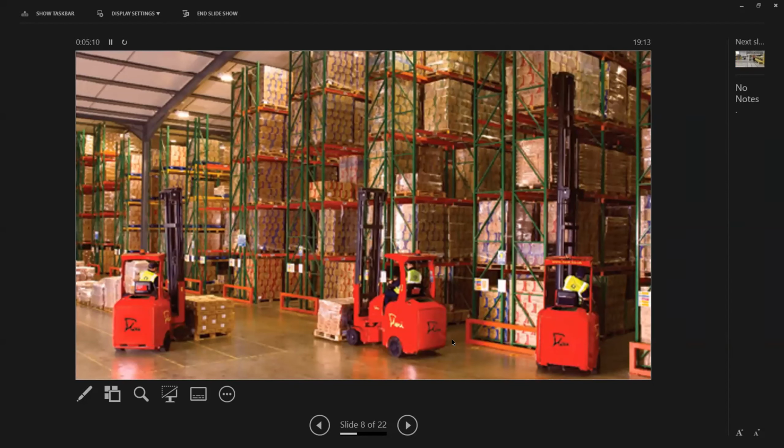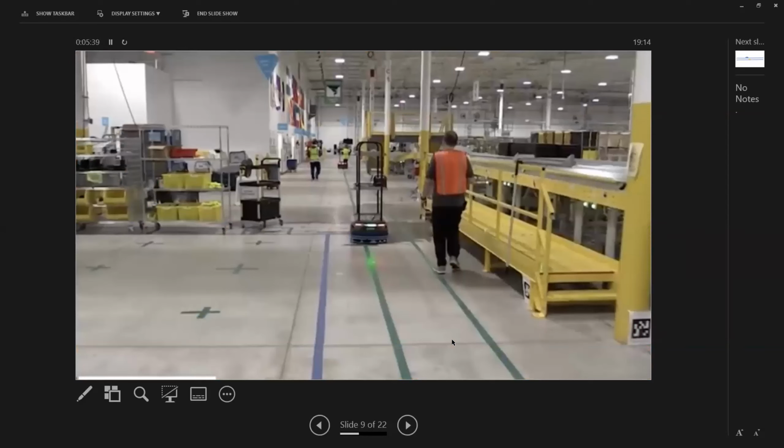The devices that actually carried the passengers around were based on these little, well, not so little, industrial robots that are designed to be controlled by a computer in a plant and use these high bay storage facilities to put boxes into particular places. And the computers know where every single one of these is because it's following tracks on the floor. And the floor tracks pulse a magnetic signal. If it's a kilohertz, it's a 0. If it's 900 hertz, it's a 1. And so it uses very slow digital communication magnetically through the floor track. And that allows both communication and for accurate positioning or recognition of positioning of each of the robots, wherever they are.